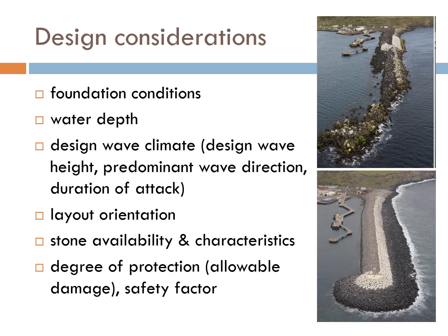In addition, the design considerations will require information of the design wave climate, which includes the design wave height, the predominant wave direction, as well as the duration of attack, which are important to determine the layout and orientation of the breakwater to achieve optimum effect.